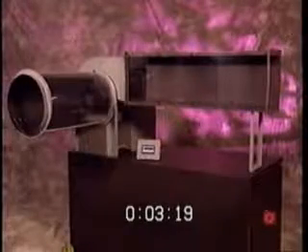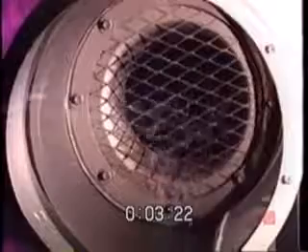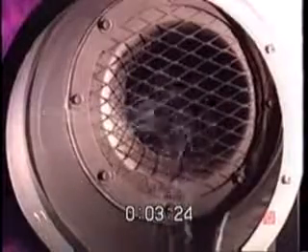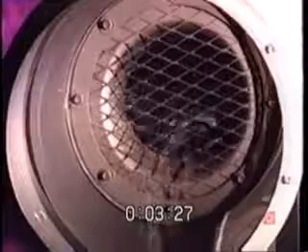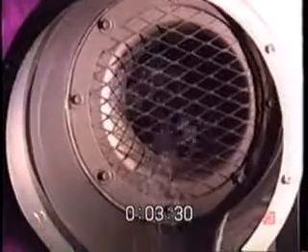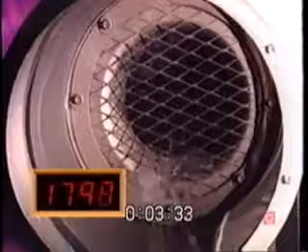In many cases, air is ducted to the inlet of the fan. For proper performance, air must enter the fan uniformly over the inlet area in an axial direction without pre-rotation. This results in an airflow reduction of less than 1%. Occasionally, space limitations do not allow the designer to provide a straight inlet to the fan. Many times, this type of fitting is attached to the fan inlet. With this type of duct connection, a counter-rotating vortex appears. In this case, airflow has been reduced approximately 45%.